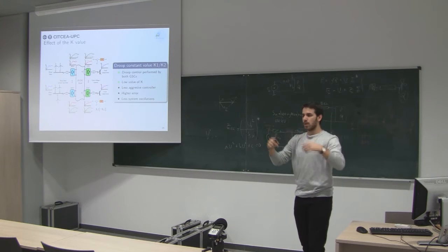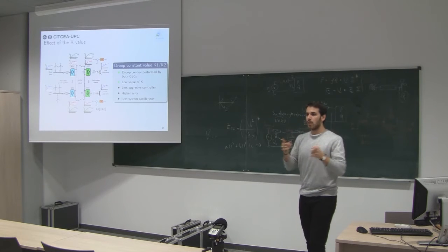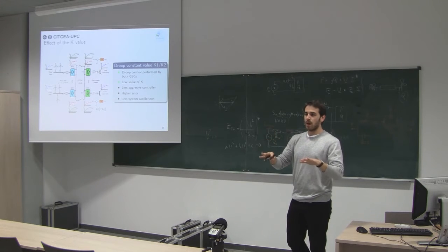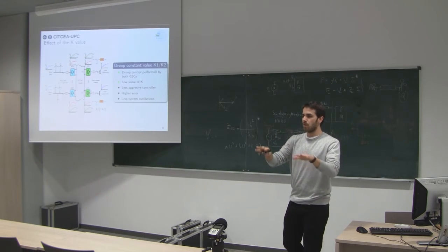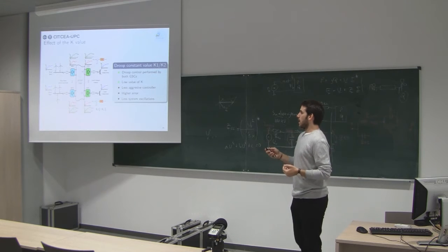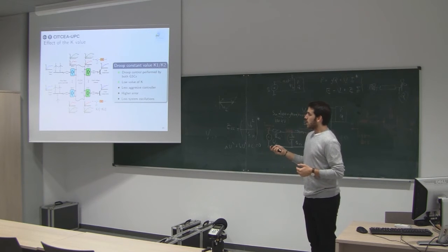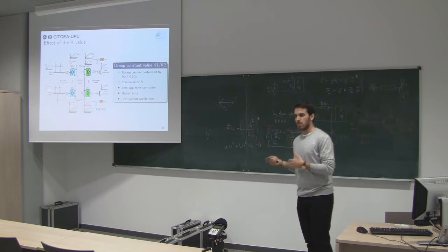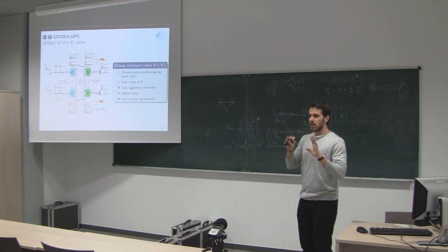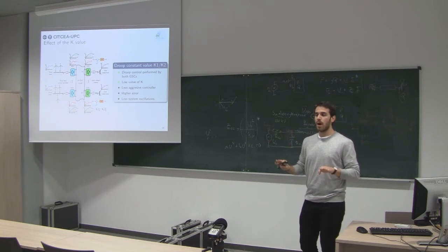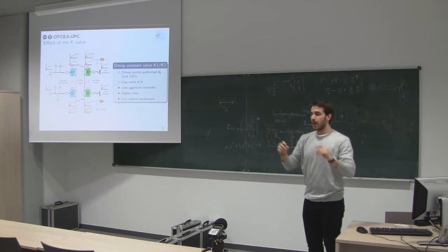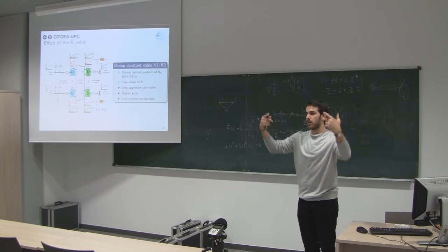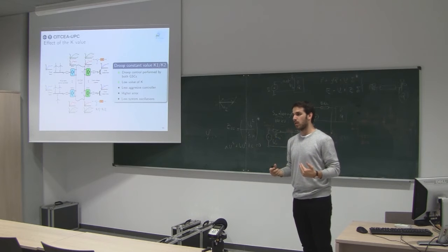If you have a large error, your control action, your power extracted, as you are multiplying by a low value of K, will go smoothly through the transient. That's what you can see here. There are no spikes on the voltage, no huge oscillations on voltage. But it can take a while to get to the steady state, and as this K is lower, the error will be higher, but you have a less aggressive controller.